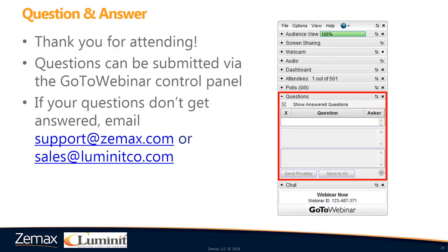Okay, in reality, with real products, it doesn't really have much impact unless it's an absorbing media. So typically in OpticStudio, most of the media is not absorbing. So I believe the impact is almost nothing. However, what I would do if you have media, let's say plastics that are other than PMMA, is put a thin layer of PMMA on top of, let's say, polycarbonate, because polycarbonate does behave differently in terms of how it refracts. So there'll be slight differences, but in other words, transmission should not really be impacted, or even the light distribution.